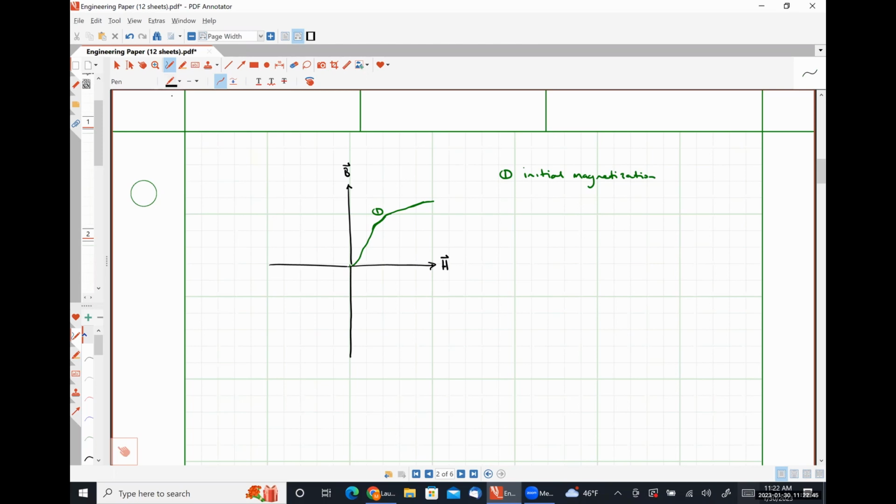There is an upper limit to the magnetic flux density strength that can be attained, which we're going to call B saturation. So effectively at this point, any further increase in B field, or excuse me, H field does not cause an increase in the B field, because effectively your field lines can only get parallel. You can't get any more parallel than parallel.